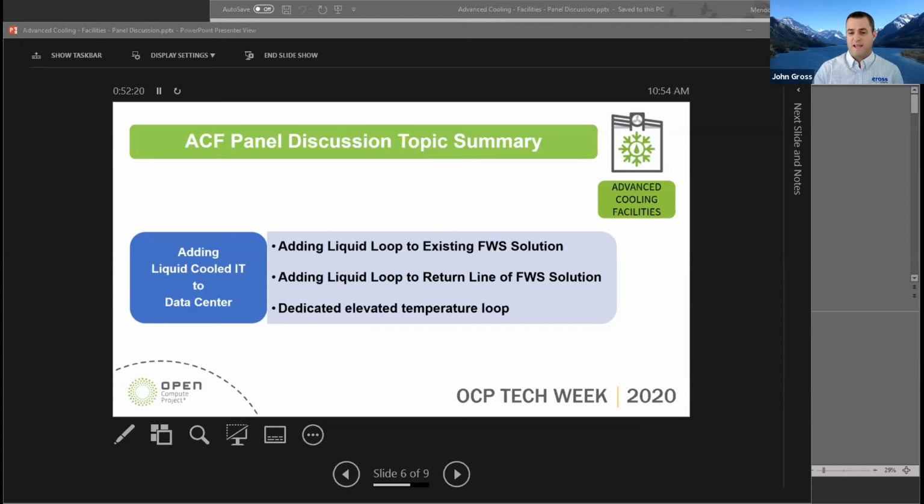And to Valley's point, and I hate to say this as a design consultant, if you go to liquid cooling, you're getting rid of the CFD modeling of your aisles and your racks and all that other stuff. You're really down to hydraulics. And if you can do that hydraulics without a chiller plant, you're dealing with pumps and fans. Yes, we still have to make sure that things like the network and storage are taken care of, but the facility can really be simplified quite a bit. Especially if you're a colo provider, and I'm sure Jason can attest to this, anytime you see your risk go down, your SLAs feel a little more comfortable.